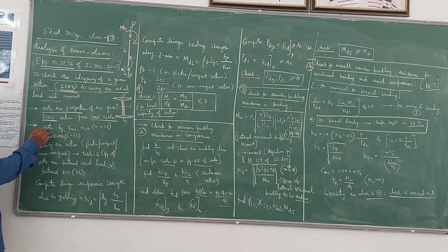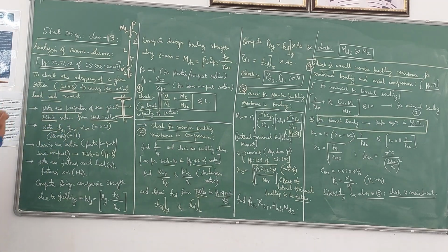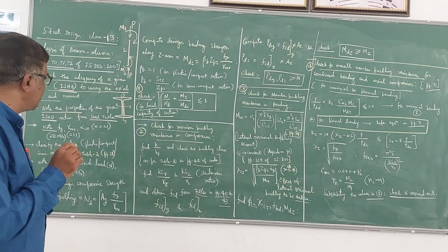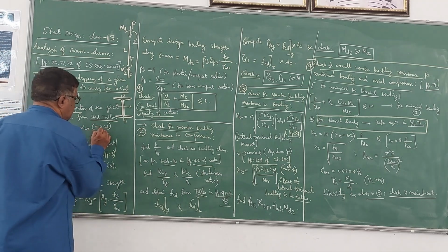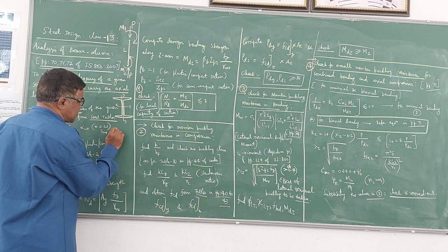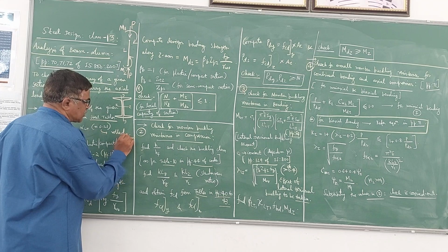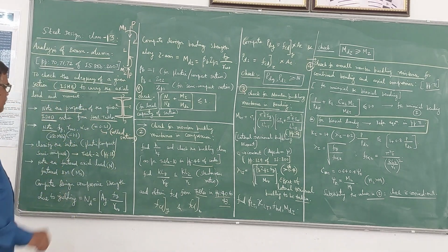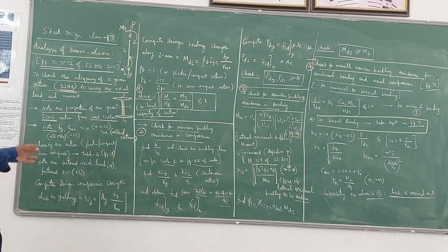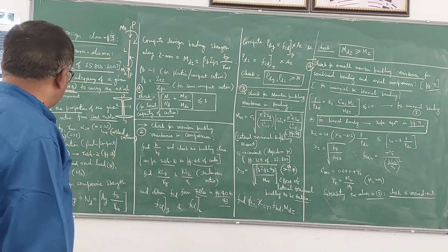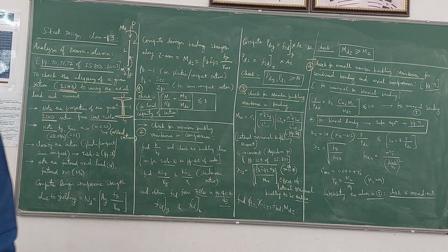Then you note down the values of Fy, gamma m0, and alpha imperfection factor. This alpha value is taken as 0.21 for rolled sections. This I have explained in the case of beams also. Gamma m0 is of course 1.1, and Fy depends on the grade of steel. For Fe 410 steel, you can take the Fy value as 250 MPa.